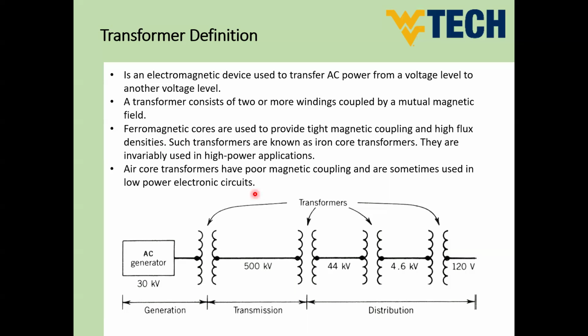You don't have any more reflected value to make the circuit function, which means we cannot use a magnetic core transformer for such a case. So sometimes we may need an air core transformer, but this is for abnormal conditions, not for normal operation. And in our course, guys, we are focusing on the normal operation of transformers. So all of our discussion in this topic will be on the magnetic core based transformer, not the air core transformer.